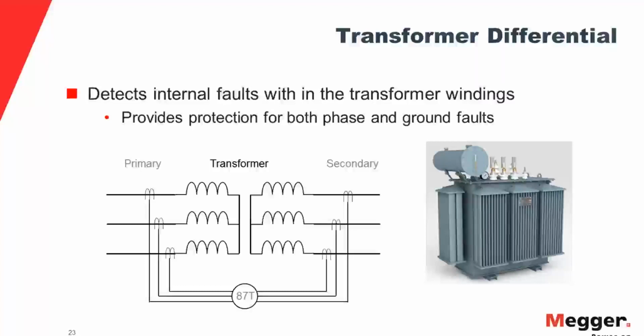So the typical settings that you will see on a generator differential are the winding pickups, the pickup value of the windings, and the time delay associated with the differential operation. This is an intentional time delay for the operation, mainly for time coordination purposes. It will also have the slope characteristics: what is the minimum pickup, what is slope 1, what is slope 2. On top of that, you also have the restrained and unrestrained pickup values.